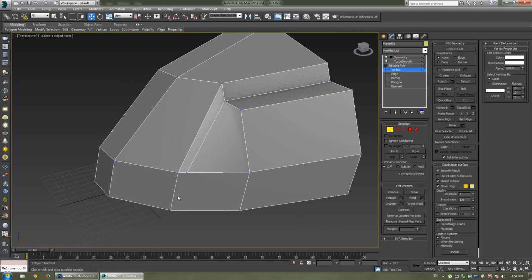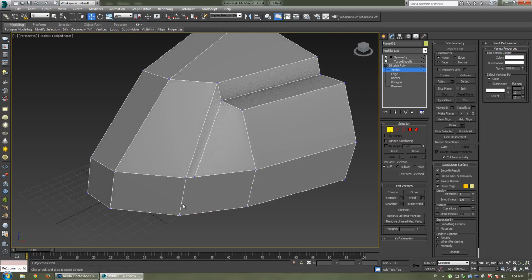Alright, so moving on. We've added this loop now and it's kind of coming down, and we can continue that down to this point here. So once again, I'm going to go to the cut tool. I'm going to click on this point. Another little important piece of information to note is when you're using that cut tool, you'll see the icon the cut tool is making at the moment is a kind of square with little dots around it. But when I touch a vertice, it shrinks and we're seeing a little crosshair. So it goes from being a square to a crosshair. When it turns into a crosshair, that's when you know you can click on that vertice and point down to an edge or another vertice.